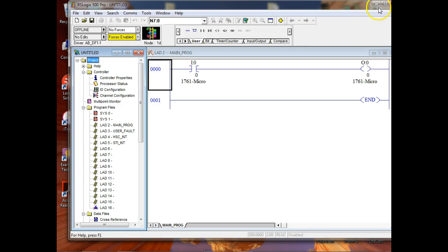This is the actual program that's in the PLC right now. By the way, it's backwards on a PLC because the PLC considers itself to be a computer, the main guy. Normally when you download stuff from the internet, it comes from the internet to your house. But when we put a program into the PLC, it's called download because it considers itself the main guy. So if I want to get a program from the PLC, I upload. If I want to send a program to the PLC, I download.